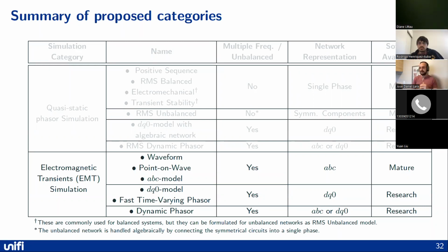And finally, the last implementation that we have is the dynamic phasors, as implemented by Seth Sanders originally. And of course, there's a challenge here because you need to define very clearly for the dynamics and the behaviors that you want to include how many harmonic components you want, right? So again, this is where a lot of researchers are looking into this to basically say, what if we include a particular number K of components to be able to model multiple frequencies and multiple effects?